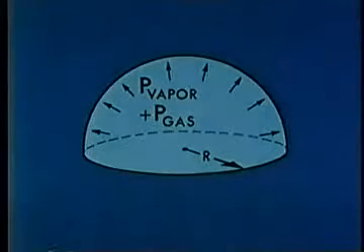as it develops. Pressures near the vapor pressure require the presence of nuclei, which contain minute amounts of vapor, gas, or both. Cavitation will occur only when these nuclei become unstable and grow when subjected to a pressure reduction. The conditions for such growth can be derived from an analysis of the static equilibrium conditions for a spherical nucleus. The internal forces produced by the partial pressures of the gas and vapor within the nucleus must be balanced by the ambient pressure and the surface tension pressure at the nucleus-water interface.